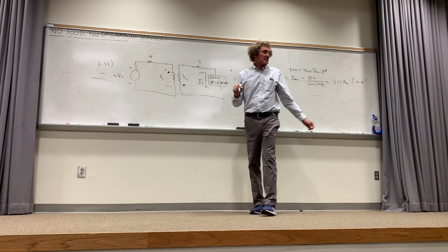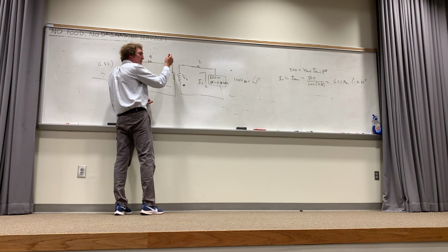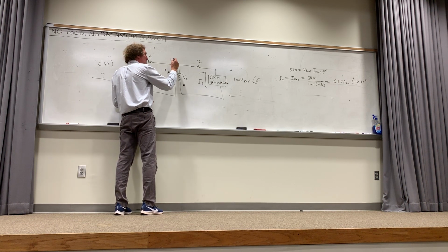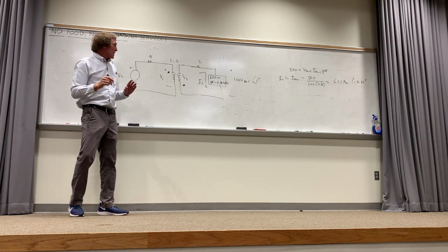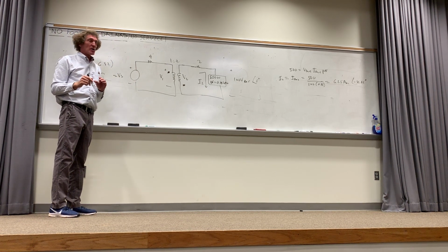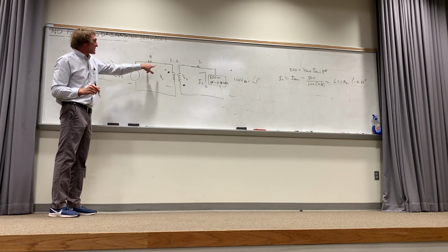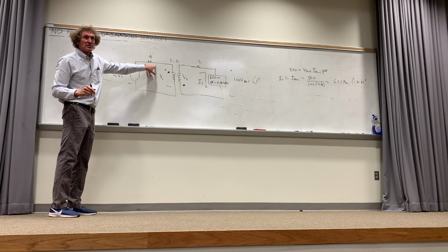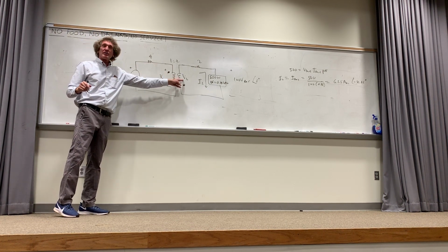Now here, I didn't get this. Can somebody just tell me the turns ratio? Is it 2 to 1 or 1 to 2 something? 1 to 2. It's 1 on primary, 2 on secondary, is that right? All right. Right away, they're after this voltage, right? Now hear me. We're going to need both the current in here and the voltage. Here's why. I need to get the voltage there, and the only way I get the voltage there is knowing the current on the primary. The voltage here is gotten by knowing the voltage there, correct, class? So please watch this.